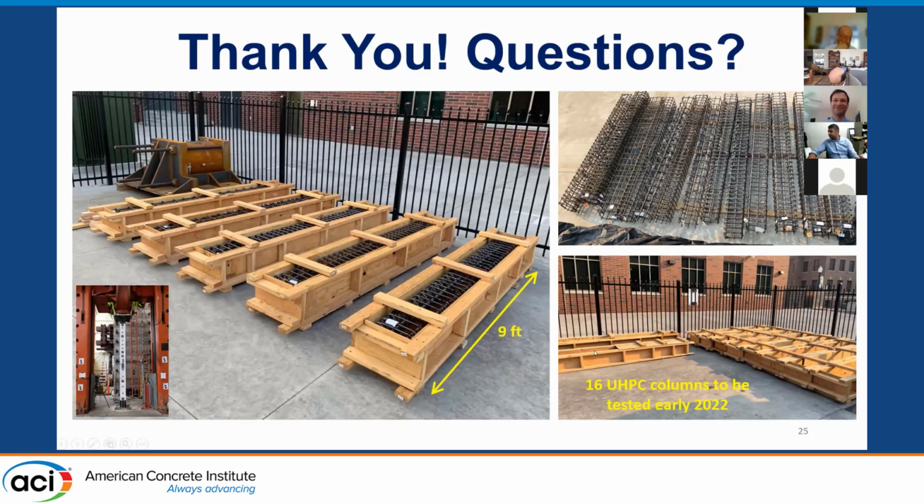Maybe just one quick question from myself. With all your recommendations, Mohammed, you said, for example, for the elastic modulus, 42,000 square root of f'c, and the other recommendations you mentioned for UHPC. In what strength range would you feel comfortable recommending those? Because I have seen in the diagram you went down to 15 KSI. So what is the strength range?